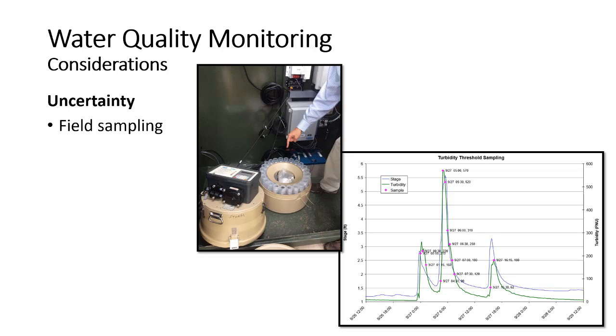We try to just connect these dots pretty simplistically, but for about 10 measurements that it took, that's pretty good, right? That's a really nice way of sampling storm flow: you connect your auto sampler to the flow measurement device and get that device to tell you across the flow ranges when you need to sample. Because if you're out there grab sampling by hand, it's pretty hard to know where the peak is, right? Like, when do I need to be taking those samples? Okay.